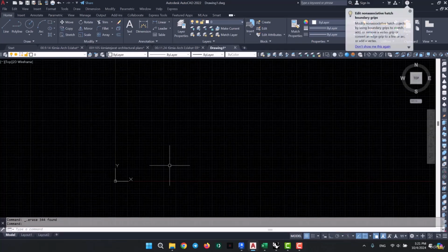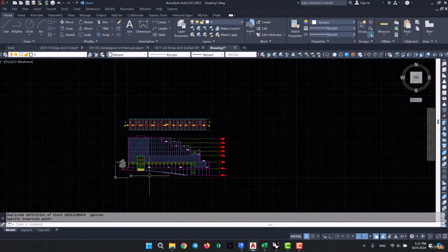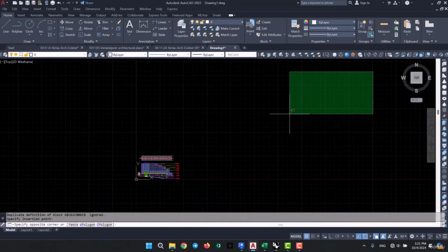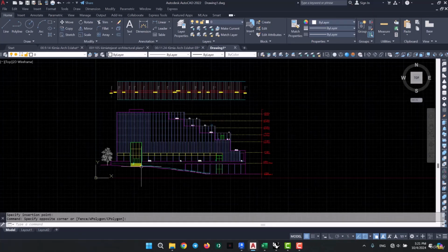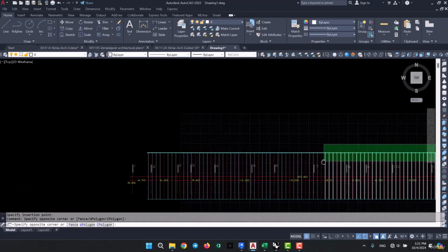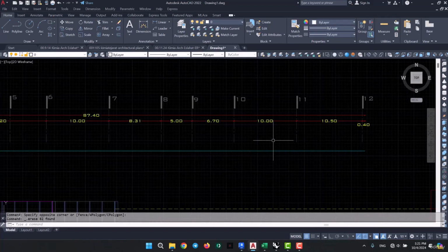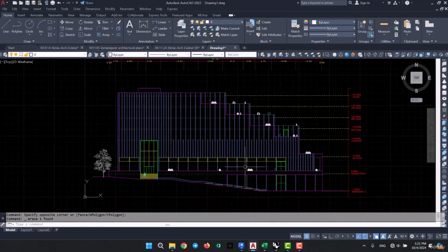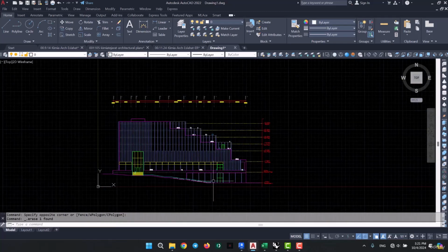And now I'm going to go over here and place it somewhere near the midpoint. So for example, if you place it over here, then you'll have to look around Revit to find it, because then it would be far from the 0 point. So that's why I recommend that you position it somewhere near the 0 point. And as for these, I'm not going to need them, so delete. I'll just try and declutter the plan a bit so that I can import it easily. We don't need this tree, and we just want to have a lighter file in size.